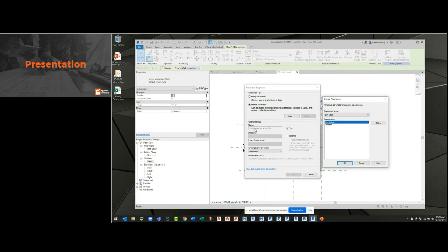It's a global setting when you update and tweak and change these parameters, right? So there's different types of parameters I'll get to in a bit, but I can go to connections here. So if I wanted to add connections for my supply air, my electrical box, and then some mechanical connections here for my VAV box, the unit height and width, etc. Right?